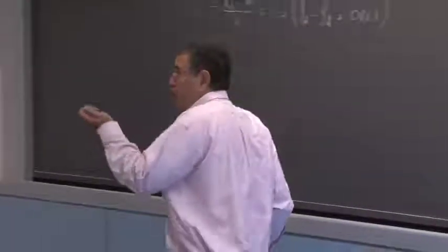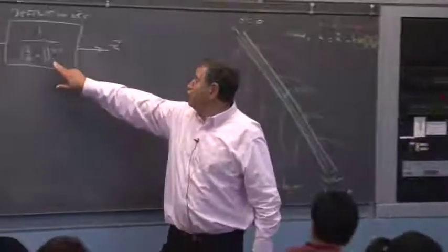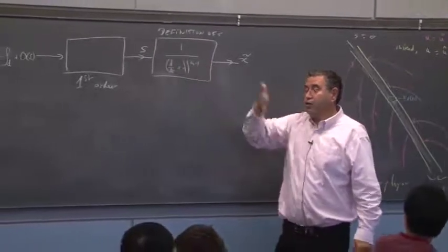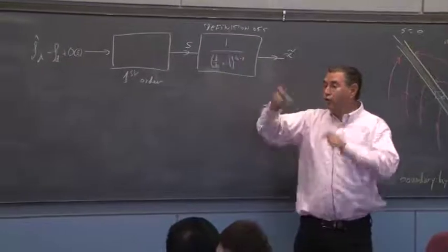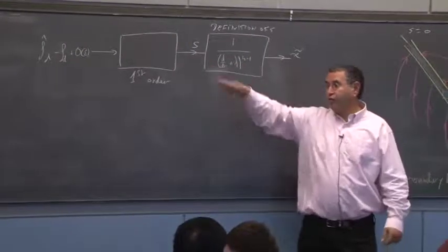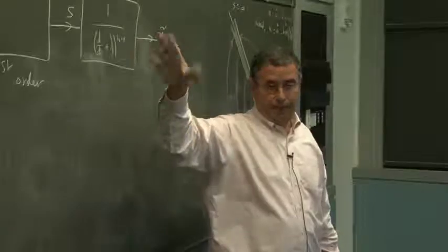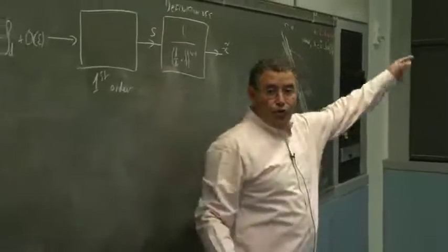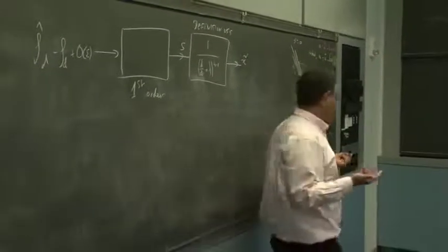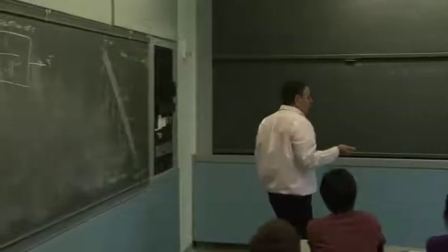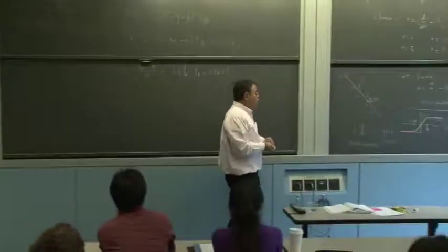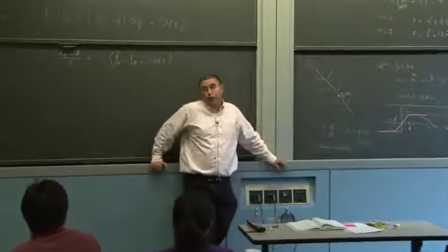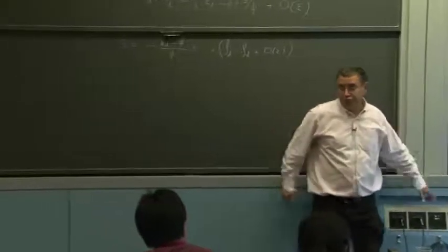Now, what can we say about this first order term? Okay, so first of all, of course, it's easy to choose lambda. We still haven't said how to choose lambda, right? But it's easy to choose lambda to be a factor 3 or factor 5 below these unmodeled fast dynamics, okay? So that's easy. The question is more this term, because this is first order nonlinear dynamics. However, we haven't yet chosen phi. Our question is how to choose phi well, right?